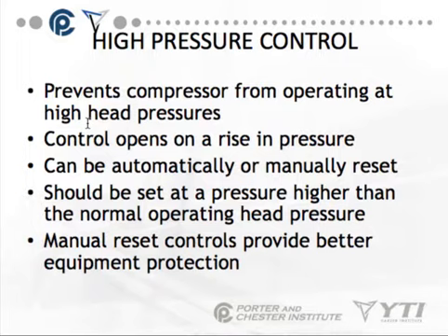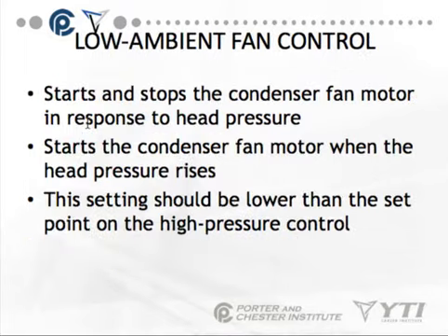Manual reset controls provide better equipment protection. High pressure controls most often have a manual reset. They will not automatically reset because we want a technician to go out there and find out why the system went off on high head pressure. We do not ever want to tell a customer where these manual reset controls are, because then you'll never find out about a problem until it's too late.